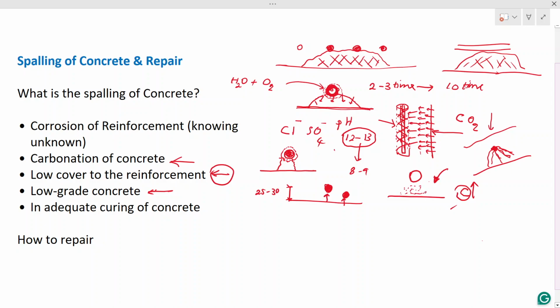So we have a well reacted concrete and also very strong concrete there. More importantly, stronger concrete has higher resistance to the penetration of harmful chemicals. The penetration of chloride, sulfate and carbonation will be resisted with the increase of the grade of the concrete, or with the creation of high resistive concrete.